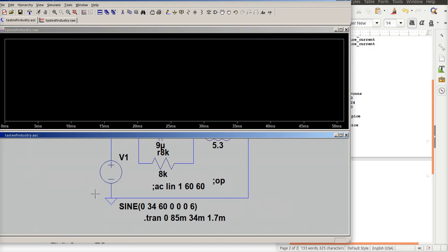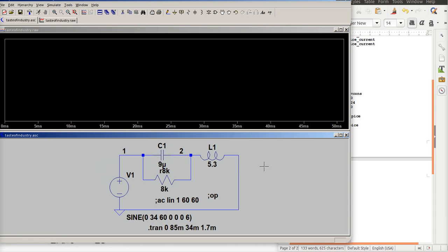And what opens up is a screen that looks like an oscilloscope. So you have a time base here, and you're basically going 0 to 51. And this is from where you're starting to where you're ending, which is actually 30 seconds or so into the simulation. So if I click down here and hit the space bar, the space bar is your friend, I can look at the voltage level at different wires. All I have to do is click on the probe. It's going to show me the voltage level at point number 1.